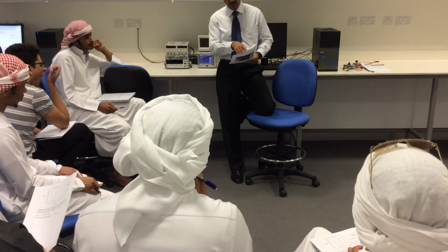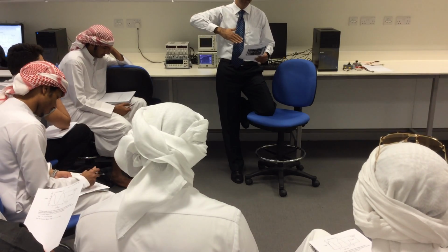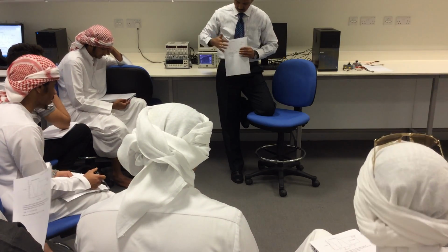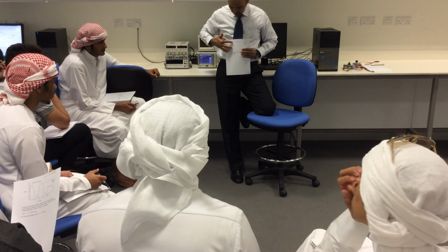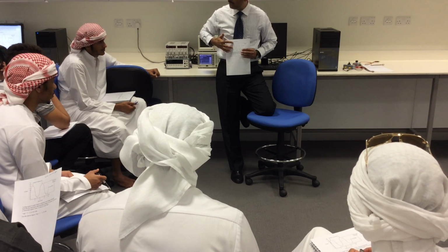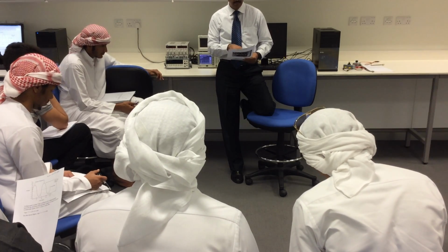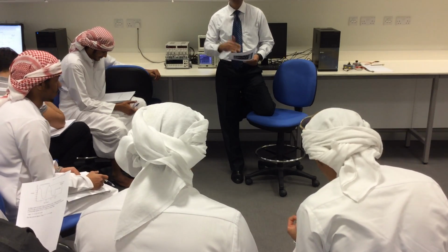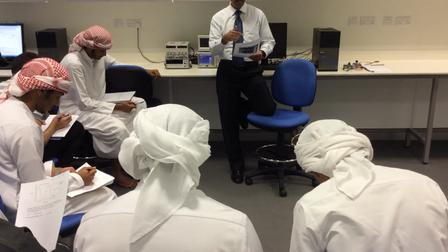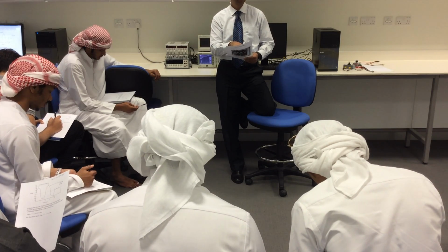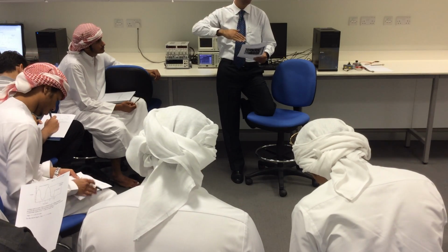Now you see the one peak voltage and the other peak voltage. There are 2 peaks, one here and the other one here. And you want to find how much voltage you have between these 2 peaks. There is a very easy formula: the maximum voltage, which is 7 on the top, minus the minimum voltage, which is 1. So 7 minus 1 is 6. So 6 volts is the peak to peak voltage.